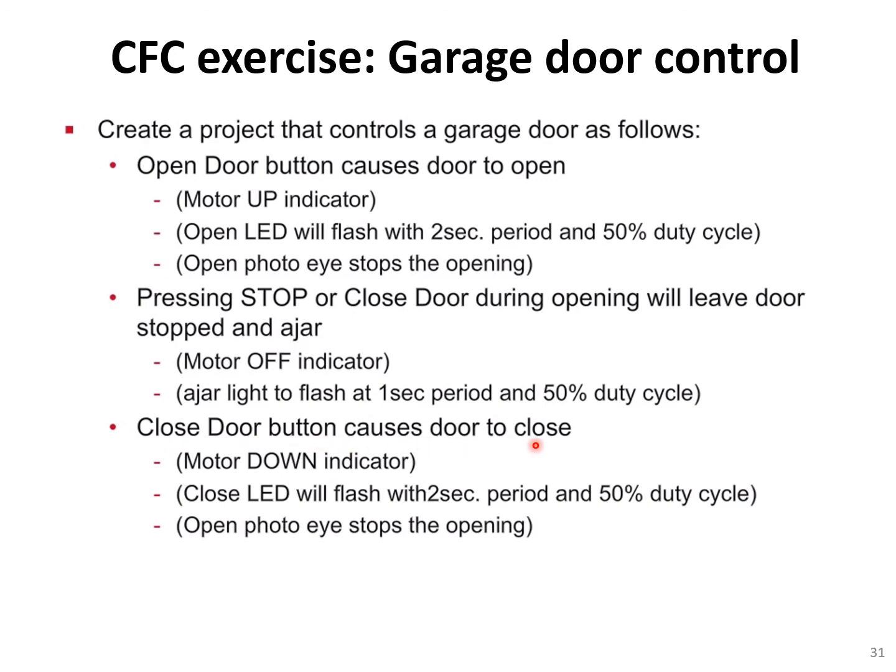Close door button causes door to close. Motor down indicator, close LED will flash with 2-second period and 50% duty cycle, and close photo eye stops the closing.